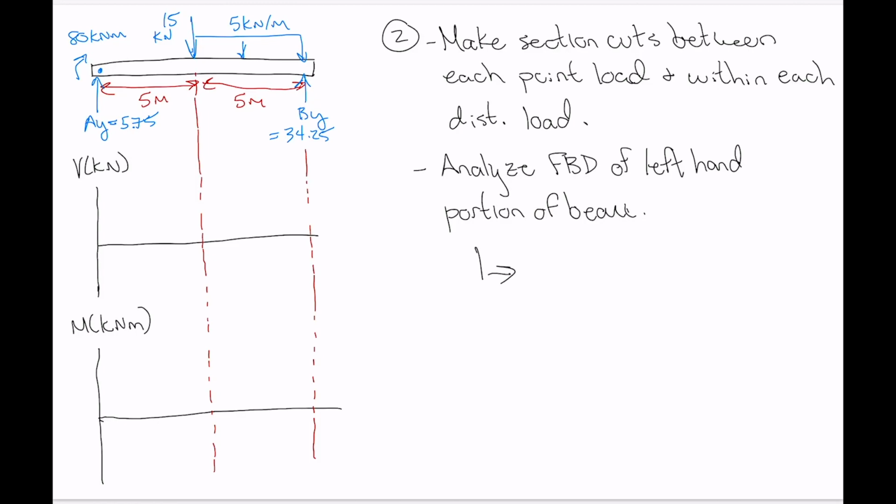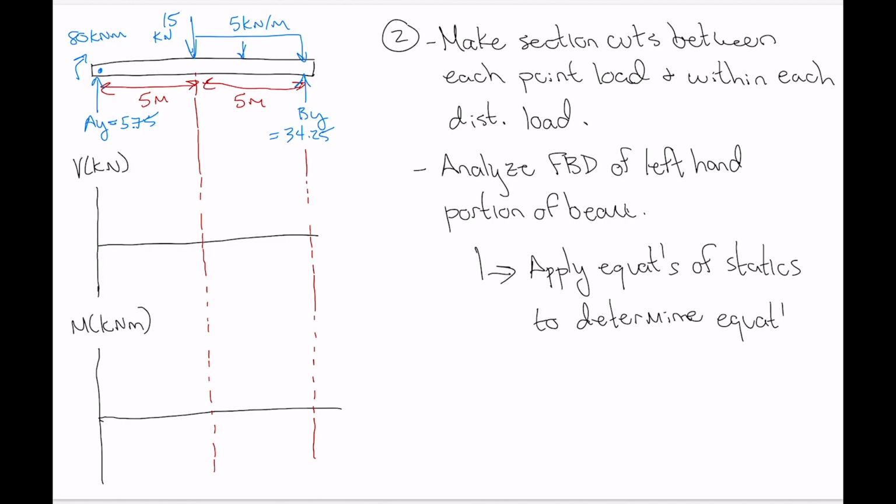and analyze here means apply equations of statics to determine equations for our internal shear and internal moment. Okay, so make section cuts between each point load and within each distributed load, analyze free body diagram of left-hand portion of beam, apply equations of statics to determine equations for V and M.